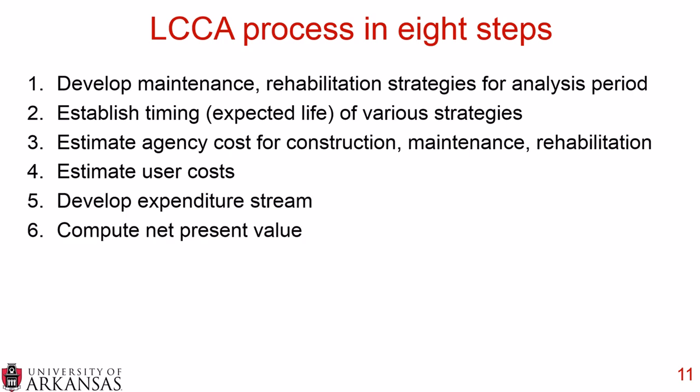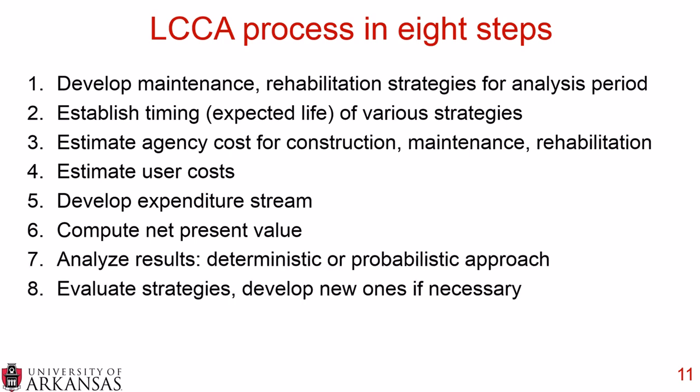You develop an expenditure stream. You compute the net present value. You analyze the results, and you can use either a deterministic or probabilistic approach. And then you evaluate strategies and develop new ones if necessary. So let's briefly walk through these 8 steps, and this will provide the foundation of the theory of life cycle cost analysis.